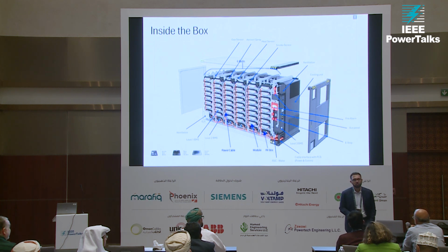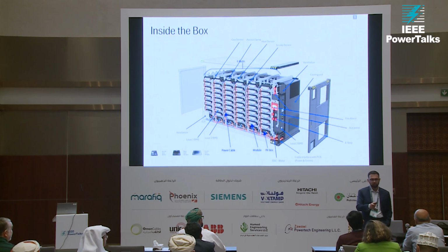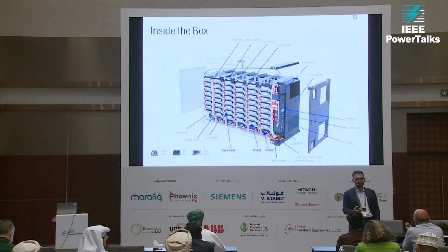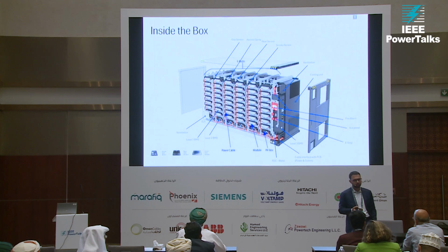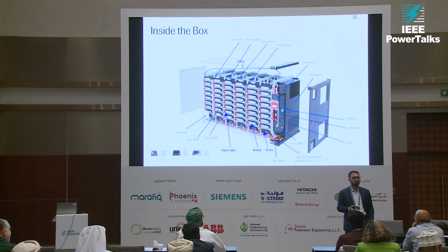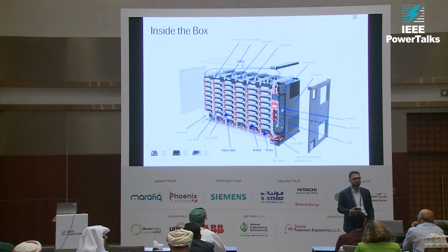Yeah, so I'm not super familiar with that equipment. Are these mitigation equipment or do they help reduce those gases? It is basically when we define the probability of the generation of gases and how it can affect the environment or how it can be converted into a fire, to avoid that, we have different classes of equipment. Because in refineries, where we are putting the battery storage for our emergency system, we define all the ventilation fans and everything based on these. It's a classification of the risk, the classification of the enclosure of the fan or any electrical equipment. So is there any classification for BESS required or not?